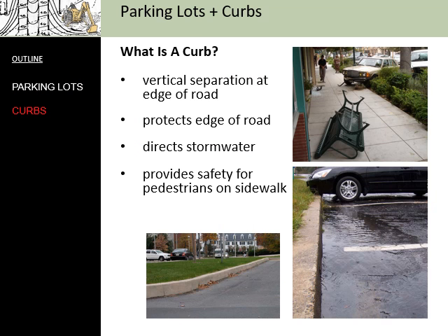So one of the aspects of designing parking lots that is often challenging for students is how do you work with curbs? The fact is, curbs are a very important part of most parking design in urban areas. They provide a vertical separation at the road edge, and what that does is a couple of things. First off, it protects the edge of the road so that cars don't drive on the edge and thereby break up the asphalt where it's on the edge of the road.